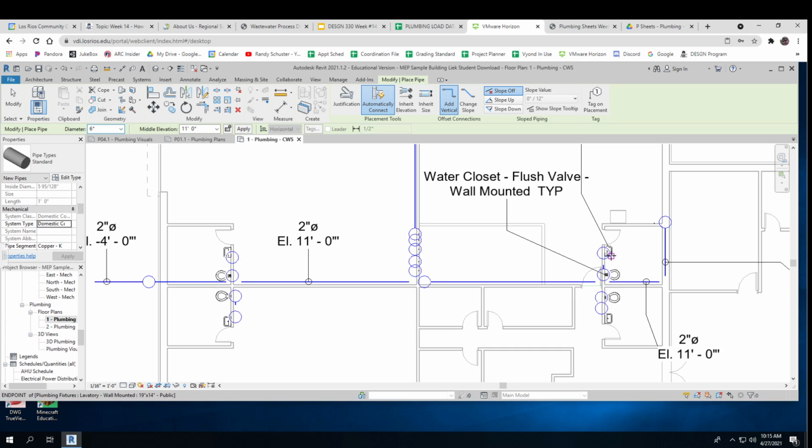So your water heater at home should be set for 125 to 130 degrees. Well, that will scald you. That's hotter than most people. I mean, there's a few people that can stick their hand under there and don't seem to be affected. But that's hot. 110 degrees is considered good hot water to wash your hands in, up to 120 degrees.